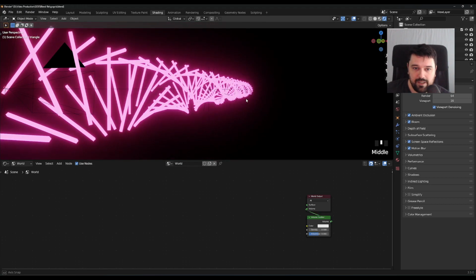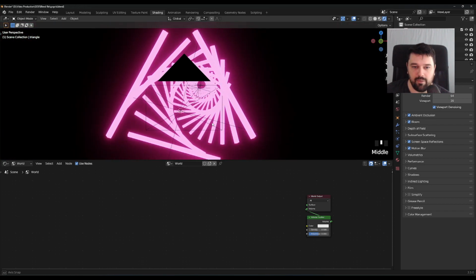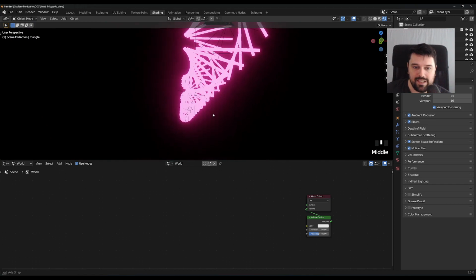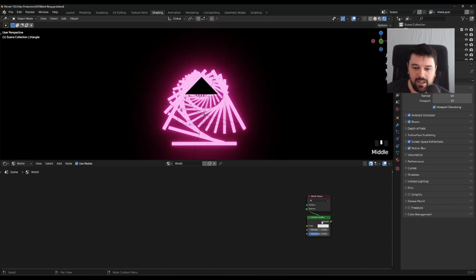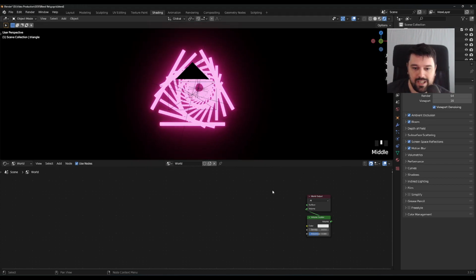the volume. Now it doesn't really change all that much. If I take it off, you'll just notice it slightly dulls, slightly absorbs some of the light and scatters it just a little bit. You could probably turn it up just a touch, but that's going to be too much. So if we bring it down to 0.01, that's probably going to be enough for the scene. It just means we can also see the background going on that we're going to create now.